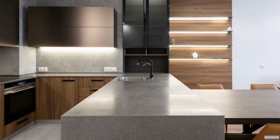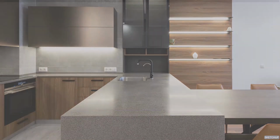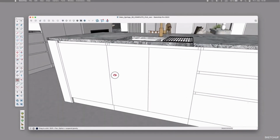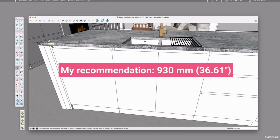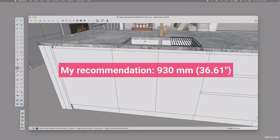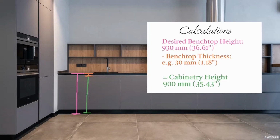In this video, we will discuss benchtop heights and depths. Typical heights for benchtops, factoring in their thickness, range from 850 to 950 millimeters. Which size to choose mostly depends on users' height. So if your clients tend to be taller, it's worth designing a higher benchtop. In my experience, a height of 930 millimeters tends to be suitable for most clients. Once you have determined the desired benchtop height, subtract the benchtop thickness to define the height of your bottom cabinetry.